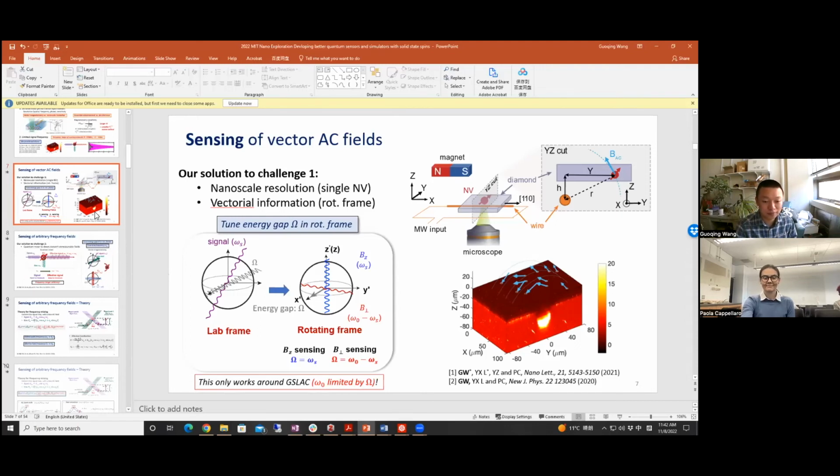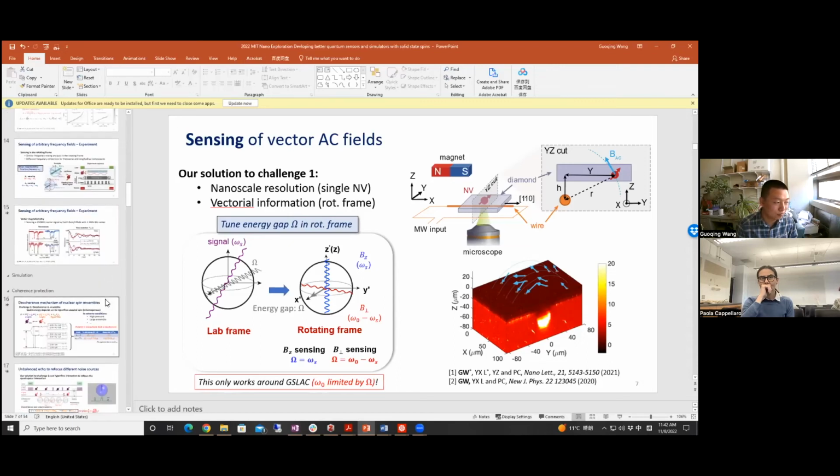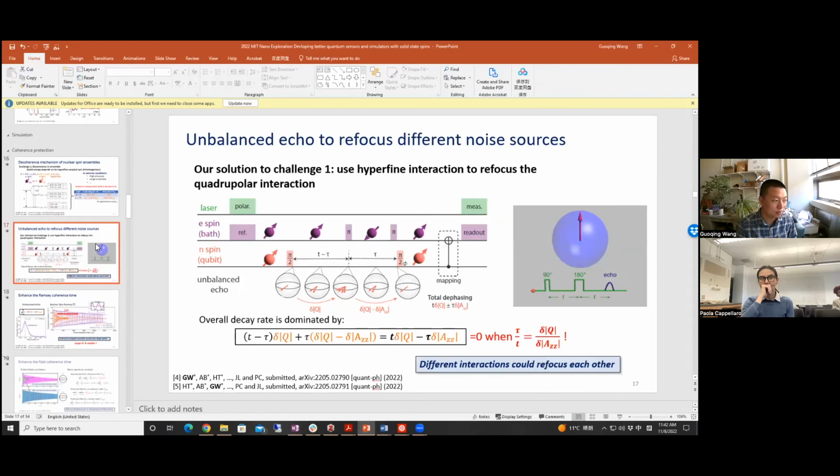Yeah. And the last question here, I'm a little familiar with the free induction magnetometers, and some aspects of your presentation remind me of that. In the free induction magnetometers using atomic vapors, like cesium or rubidium cells, you actually measure the frequency of oscillation to get the magnetic field. And people have been achieving picotesla per root hertz of sensitivity there. Okay, so in your case, it seems that you measure amplitude, not so much frequency of the oscillation.